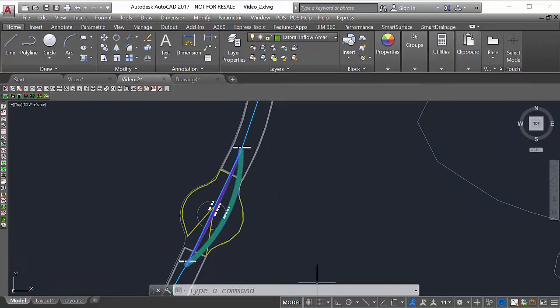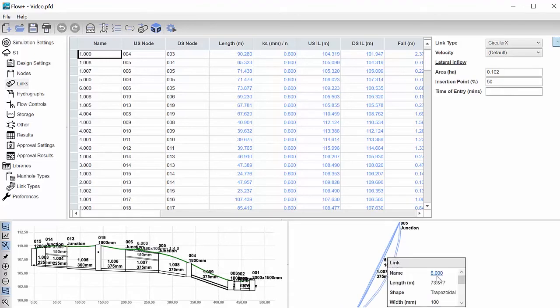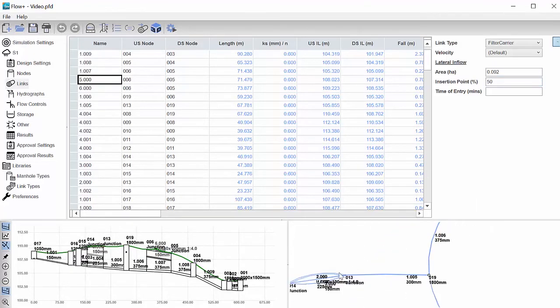Catchment to node link midpoint tolerance is a distance that is used in assigning catchments to nodes or links. We will describe how it works with some examples. All catchment boundaries must be drawn as polyline entities on layers that match one of the wildcard masks just described. To accommodate varied user preferences, Smart Drainage can handle several options. The catchment boundaries may be closed or slightly open by not more than the link to node tolerance.